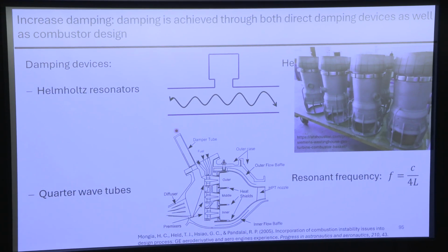It's a really good question. So the question is, do you put these in proactively, or do you have to retrofit afterwards once you've found an instability for fun? And the answer is you really hope you can put it in proactively, right? So these haven't gone on an engine yet. What they probably did was a thermoacoustic model, tried to get rid of a frequency, just couldn't, and said, all right, let's just put a bunch of dampers on and that'll help.